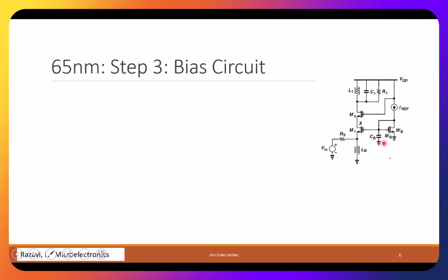And now the bias circuit. We don't have much time, so if I were you, I would just follow what is given in the suggestion, right? For the biasing circuit, we don't need to consume too much power. This guy is already taking 4 milliampere. I need to bias it with a certain current, and last time I said maybe just take 1/4 of it. So how about we take 1 milliampere. You can just put 1 milliampere there as the reference.